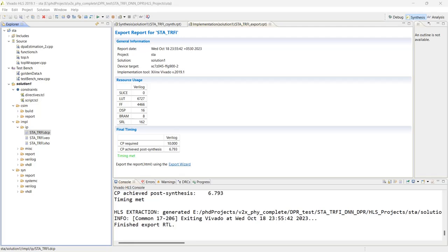Now, before we move on to create the Vivado block design and other things, after generating these we will first create a blanking configuration. It will have a top module, but it doesn't contain anything within, a black box configuration.